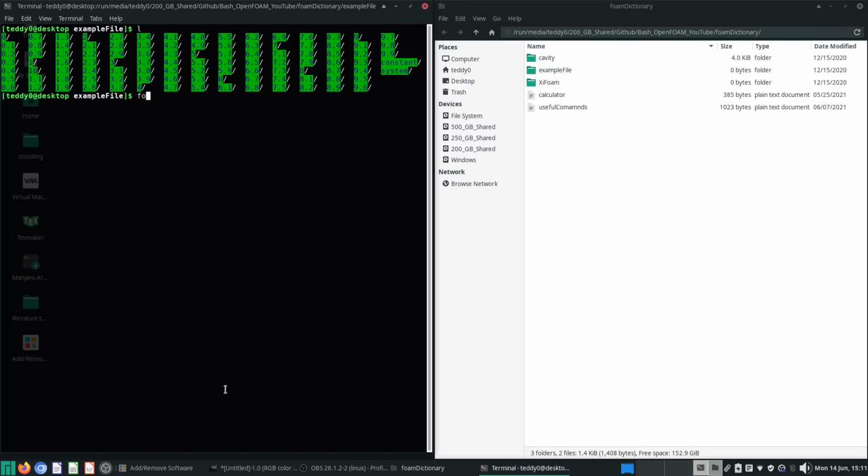So how do we clean it? Well, we can use foamCleanTutorials. This script actually cleans the files up very nicely. Okay, so this is roughly how we want to play with our system. So we run blockMesh and OpenFOAM and it works. Now this actually works fine for the first 10 seconds, but of course you want to change some boundary conditions.